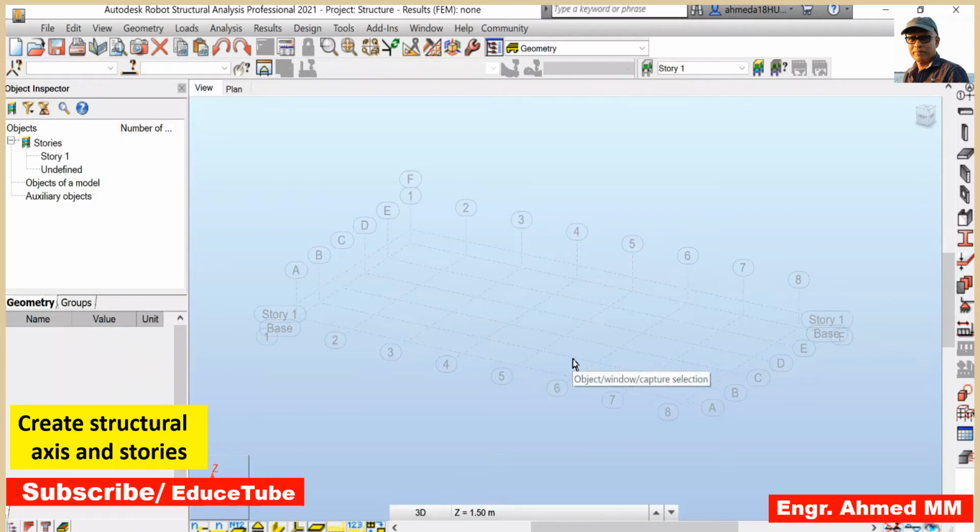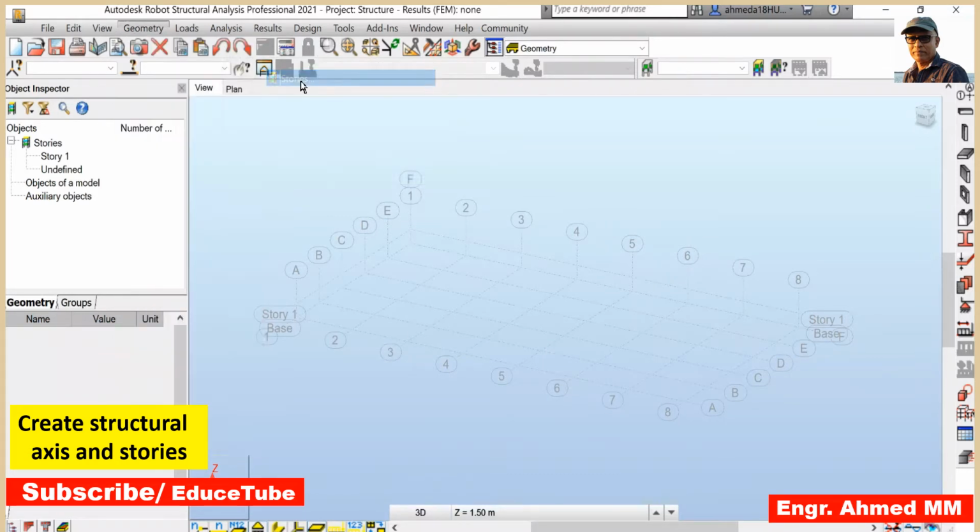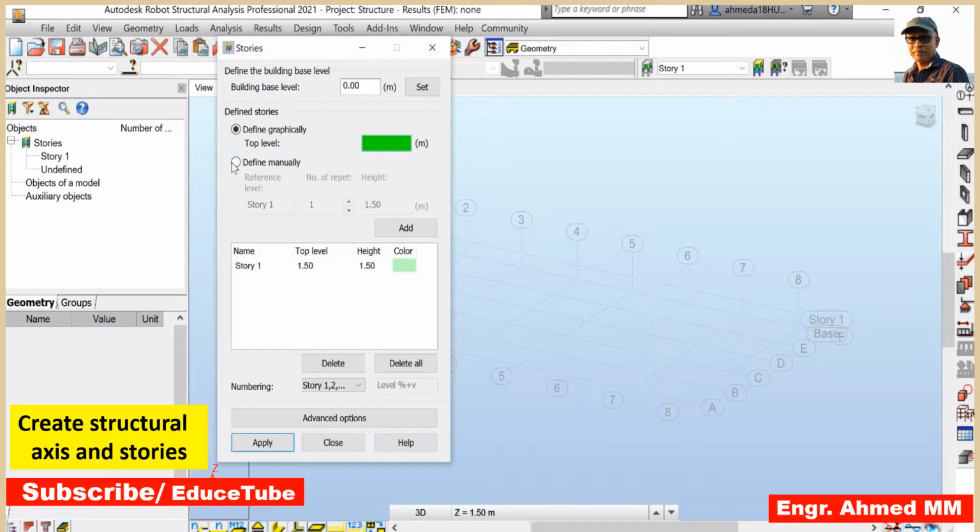Now our target is to create stories. So menu bar, geometry, stories, click stories, define manually. Here is story 1.